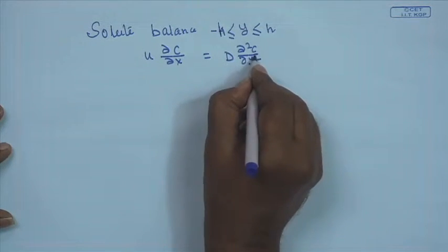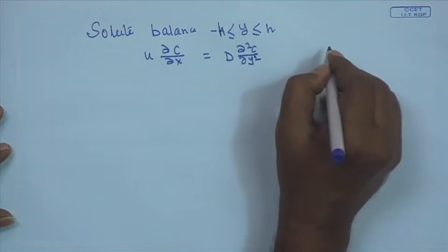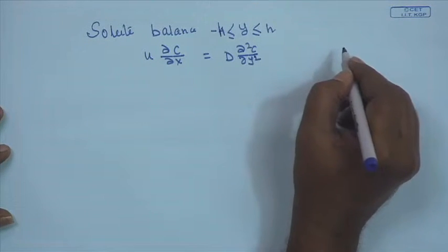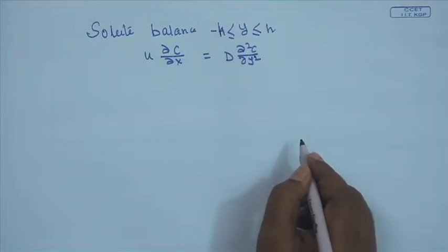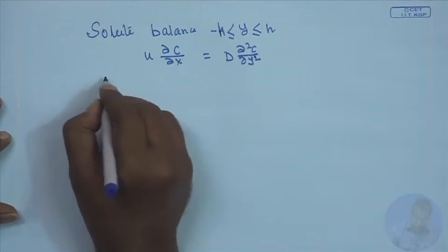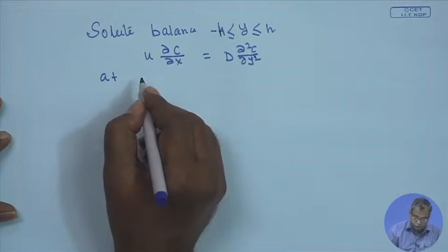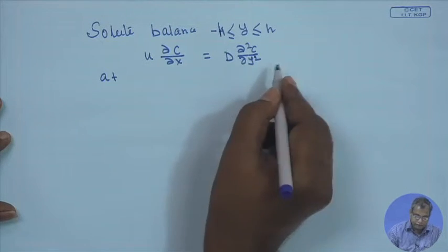Now, this is an ideal dialysis process where the only driving force appearing in the system is the concentration gradient. Unlike the earlier cases, the pressure driven membrane based processes, we do not have any pressure operating in the system. Therefore, there is no convective flux in the y direction. We will have the solute flux in the x direction only. So, no v ∂c/∂y term is present in this equation.